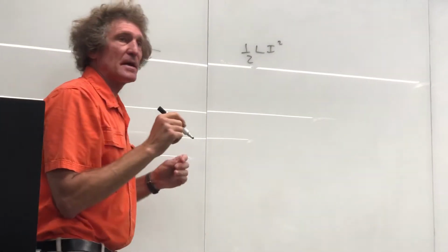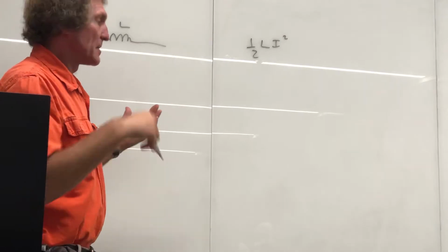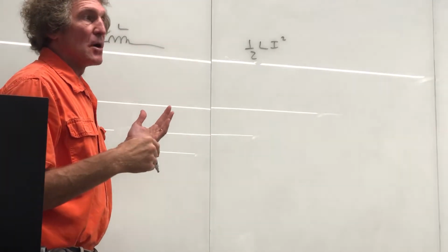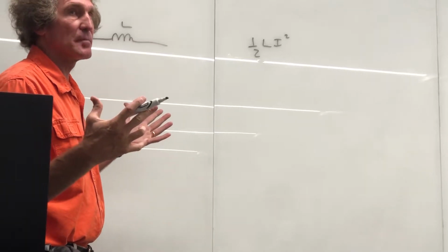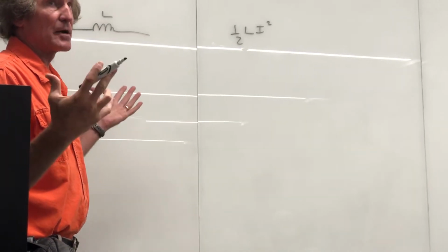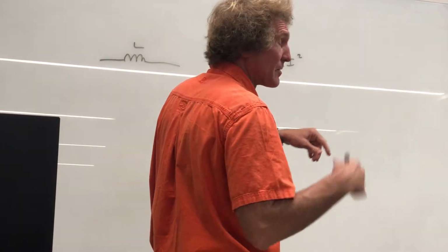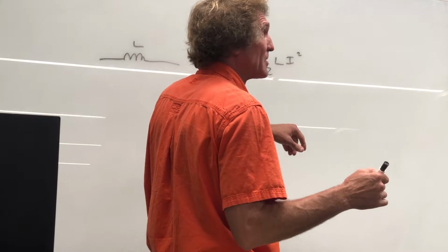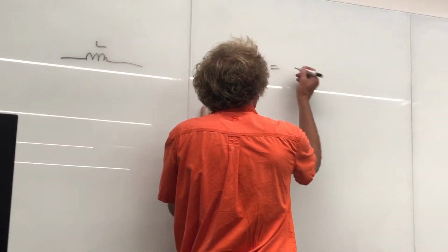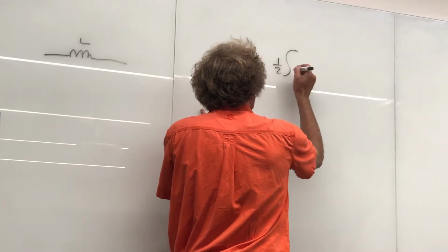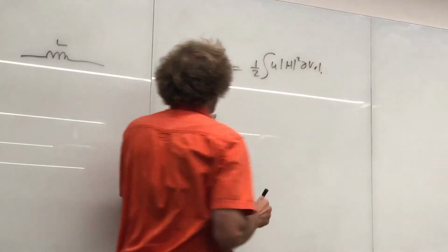But that represents any possible scheme of wires, usually wound around something, where magnetic energy is going to be created by current flowing in there, and that energy can capture the value of the self-inductance, which is L. 1/2 Li squared is equal to 1/2 times the integral of mu times h squared over the volume. And we did that last time.